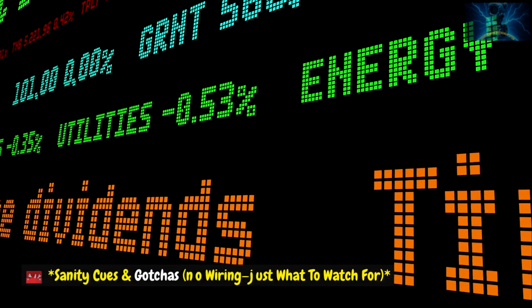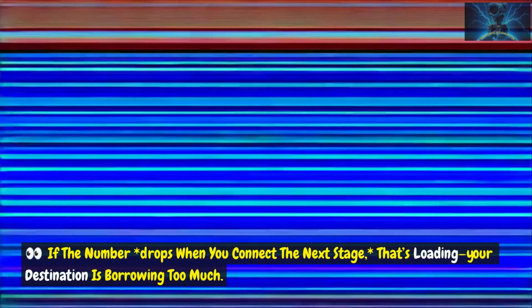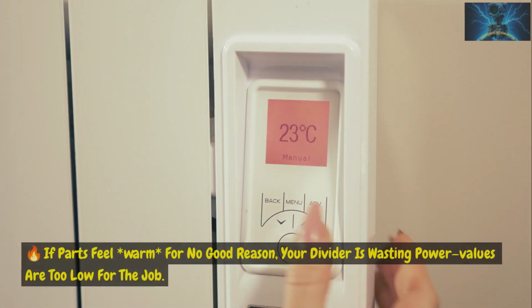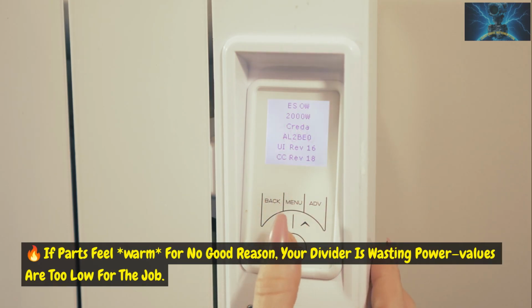Sanity cues & gotchas. No wiring, just what to watch for. If the number drops when you connect the next stage, that's loading. Your destination is borrowing too much. If parts feel warm for no good reason, your divider is wasting power. Values are too low for the job.